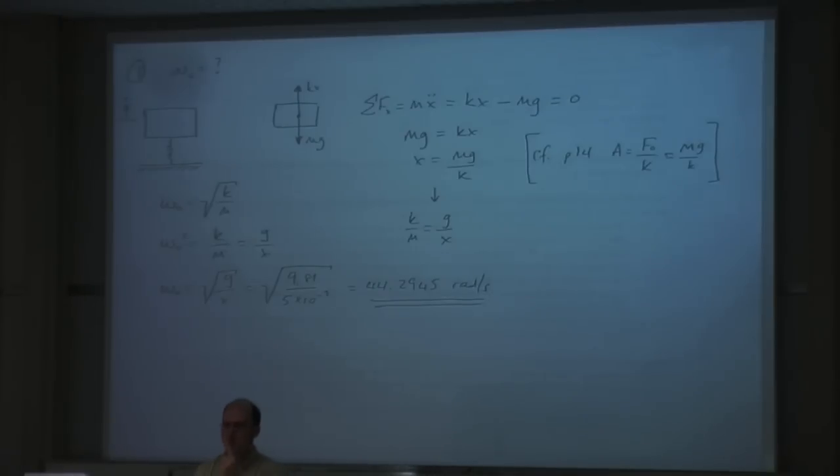So we've only been given one piece of information in that problem, that's the deflection at 0 frequency. So you think, well, how on earth can I go about solving for natural frequency? Surely I need the stiffness and the mass. Well, you don't need the stiffness and the mass. You need the ability to think, hold on a second, what do I know and what can I work out from what I know? So in these sort of situations, it's worth going from first principles because then you can understand what's going on.